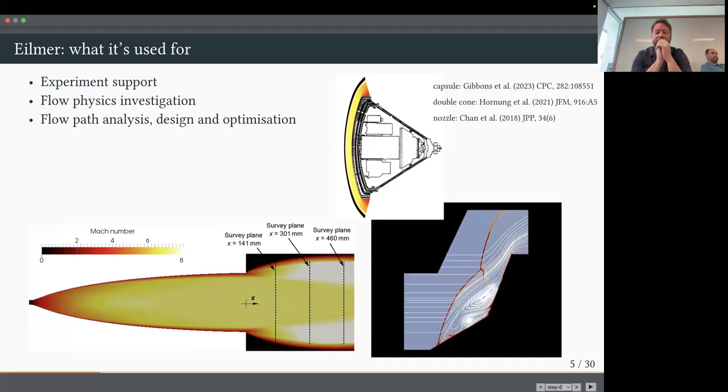It's a hypersonic nozzle for a reflected shock tube facility, a shock tunnel facility in this case. So the simulations support experiments by actually characterizing the flow in the facilities. And then we also use the code to support the business end of the experiment, so to speak.